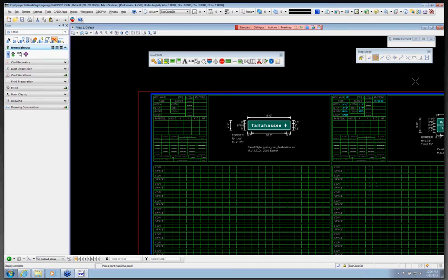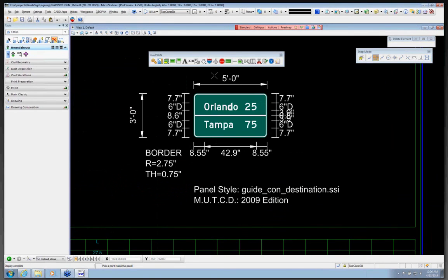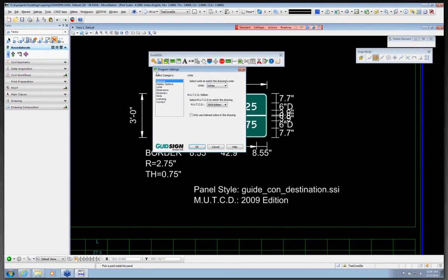There were a couple questions, I believe, about how you handle the overlapping dimensions. What's the best way to handle that? I understand. With the overlapping dimensions, you can actually come in and underneath your dimension scale, you may need to change or lower the scale, because it will automatically set to what we had set the plot scales to.